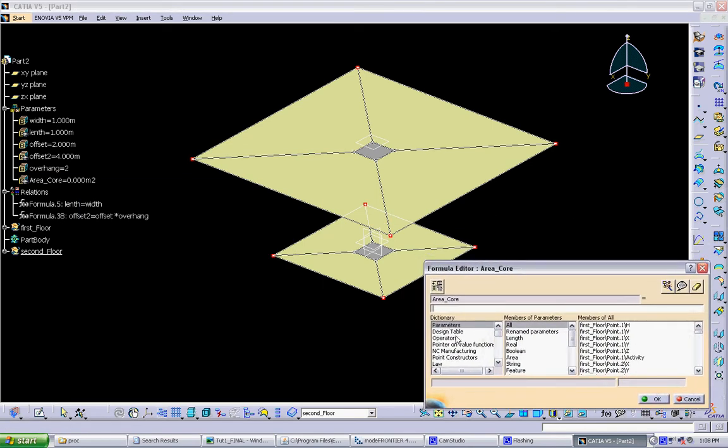And in Catia, under this dictionary, there's all these different commands that you can use. And the simplest one you can use is measures. And here you can see the syntax for how to measure different things in the model. So you can measure distances between two objects, lengths of curve type objects, and then here you can do areas. And this will tell you what kind of object it's looking for in the parentheses. So we want to measure the area of a surface, so we double click it to put it into the window, and then it will have the tooltip inside parentheses.